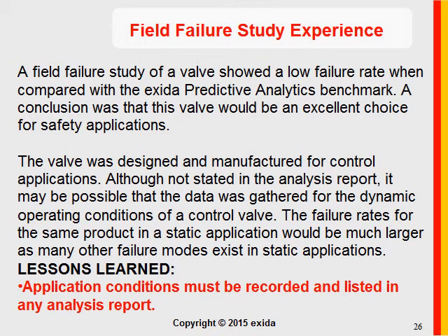I have a whole lot of stories, and you don't want to hear them all, but I've got one more. A field failure study of a valve showed a very low failure rate when compared to the Exida PA benchmark. The conclusion was this valve would be excellent for safety applications. And we discovered that the valve was designed and manufactured for control applications. And in the analysis of field failures, nobody ever recorded whether the device was being used in a control application or in a safety application.